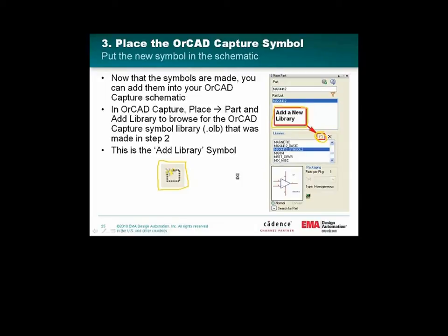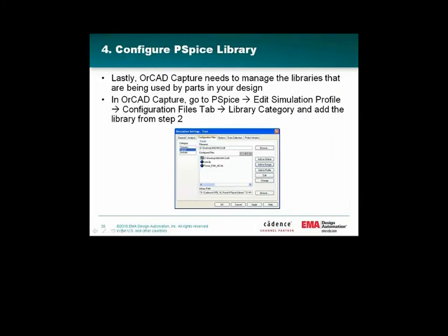And the last step is that you just need to configure your PSpice library. The Capture project is the thing that manages where all your libraries are, where all the intelligence for all the different parts resides. That's managed in the project. So the project needs to be told where that library file from step 1 is. You need to go into the configuration files and add the library that you made in step 1.